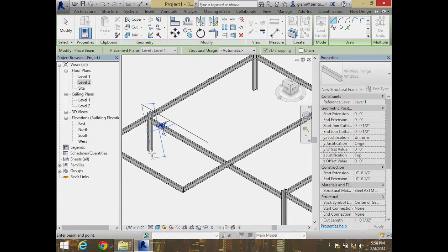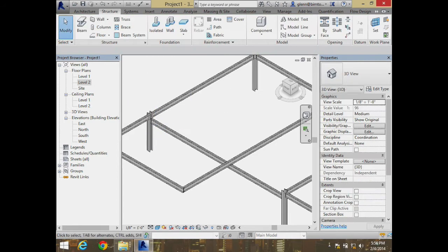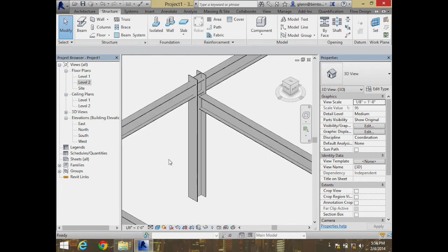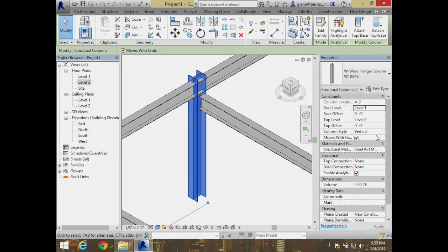Yeah, with that one. What I've got to do there is change it up a little bit over here. Really, in terms of the way to think about this, if I want the continuity of the beam coming across, what I actually have to do is stop that column underneath the beam. I need to put some plates in the beam to transfer the loads up through it. But what I would probably do here, so I can get the continuity of the beam, is take this one and lower the top 12 inches, or no, it's 12 plus 5 inches, because it's minus 7, because of the two different things added together.